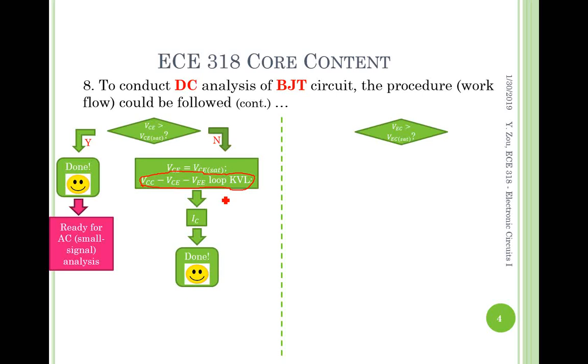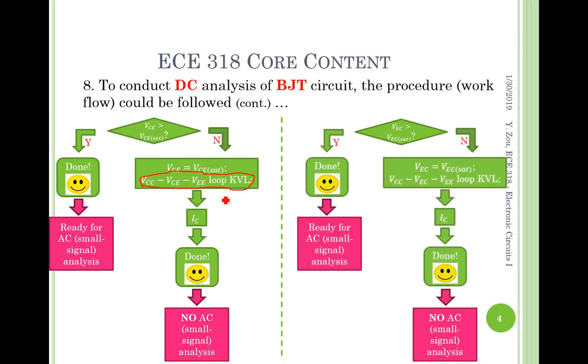However, just like in the MOSFET circuit, this is the saturation region for the BJT, so this is not an amplifier. No AC analysis is needed for finding the voltage gain. Similarly, along the other route, we have the same idea and same procedure, except the variables. Okay, that'll be all for the DC analysis for BJT, covering two types of BJT component.